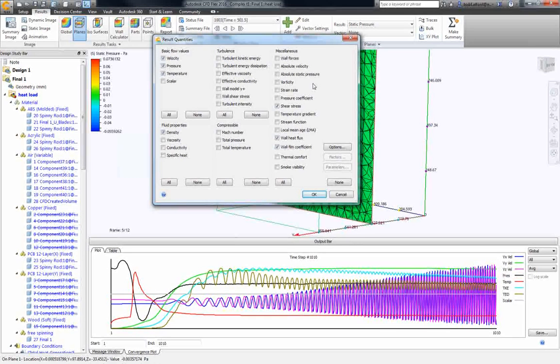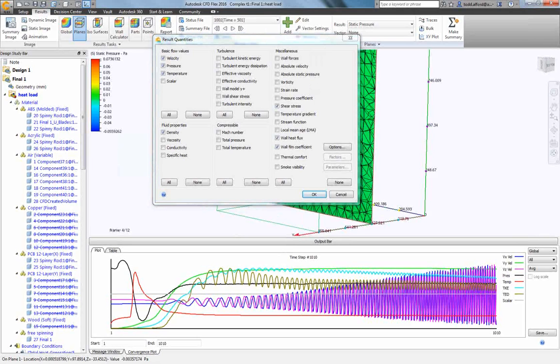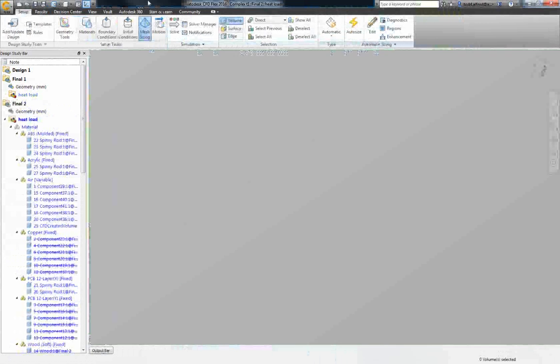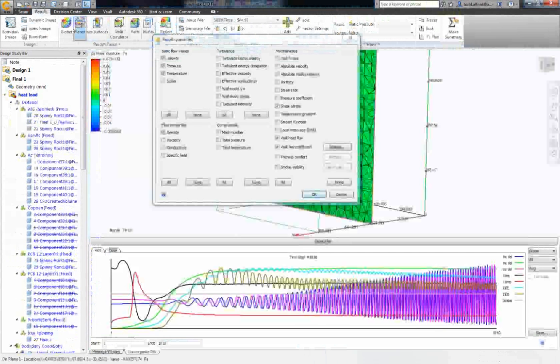So some of this might be driven more on legacy than anything else. When machines were slower, we're passing a lot of information with every iteration that's solved for on your desktop computer. And if you have more result quantities being passed from the solver to the UI, everything will slow down. So initially, only a small set of the key values like velocity, pressure, and temperature are actually shown live. And then everything else is shown after the fact, just for speed's sake and efficiency of data processing.